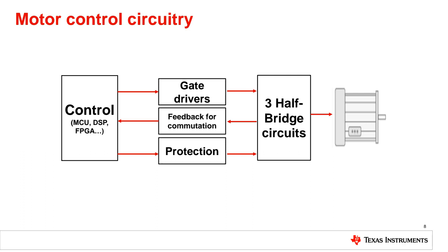Your circuit detects these signals, and it will decide using an algorithm in your microcontroller where am I. The motor tells the microcontroller where am I: 60 degrees, 120 degrees, 180 degrees, where? The Hall sensor gives you: you are here, you are here, you are here. Depending on your Hall sensor position, you will generate which coil will be active.